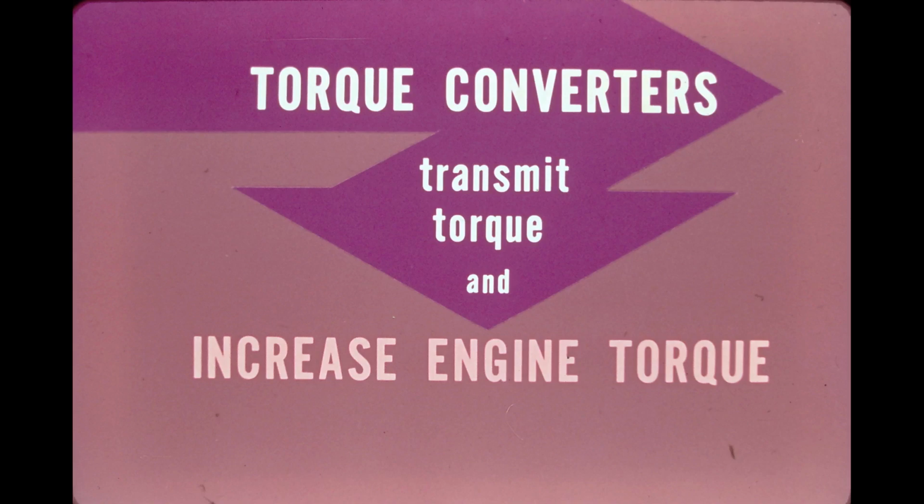All the facts we just reviewed also apply to the torque converter. Let's now see how the torque converter differs from the fluid coupling. In function, the torque converter differs from the fluid coupling in that the converter not only transmits torque, but also increases engine torque if necessary.